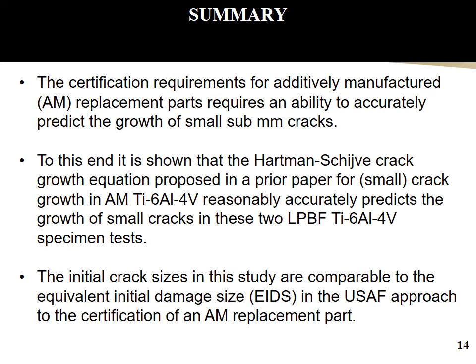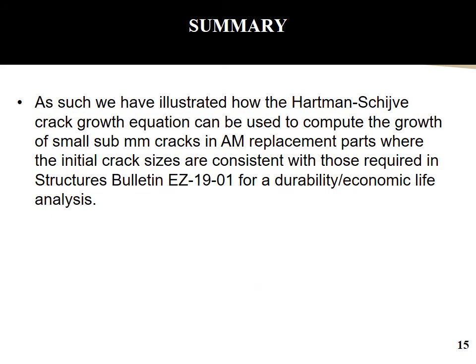The initial crack sizes in this study are comparable to the equivalent initial damage size, or EIDS, in the United States approach to the certification of an AM replacement part. As such, we have shown how the Hartman-Schwalbe equation can be used to compute the growth of small sub-millimeter cracks in AM replacement parts. Here, the initial crack sizes are consistent with those required in the Structures Bulletin EZ 1901 for a durability economic life analysis.